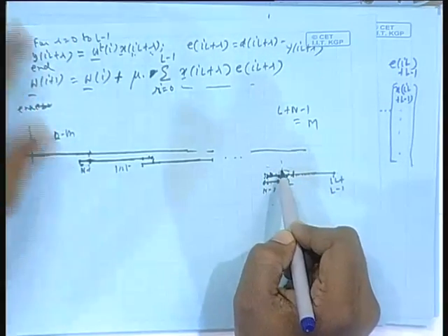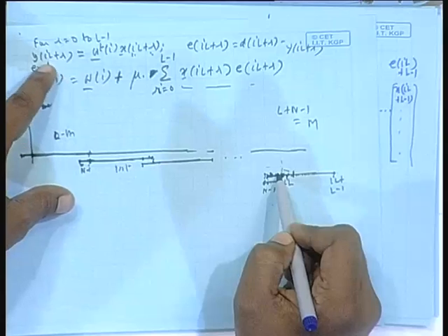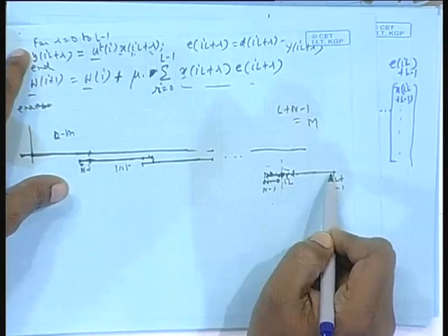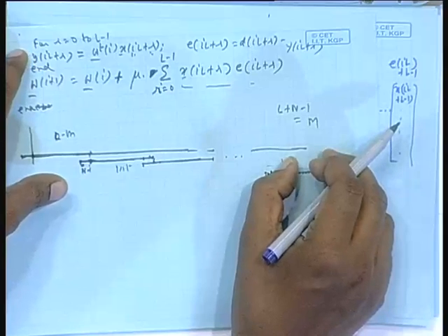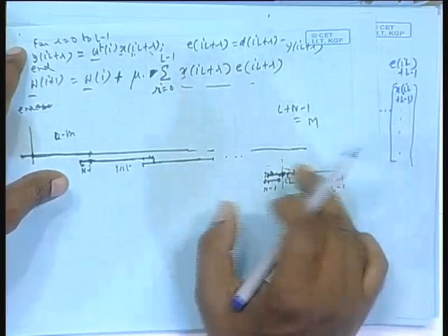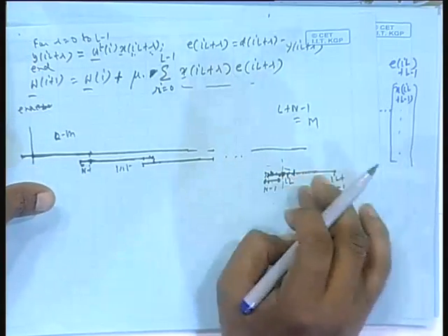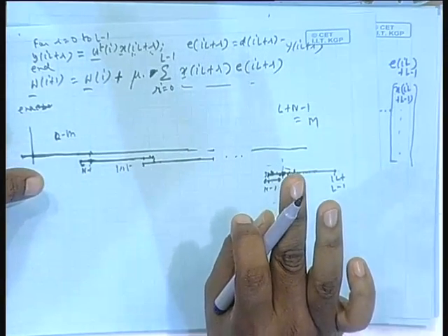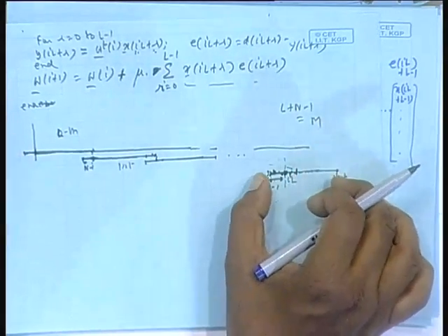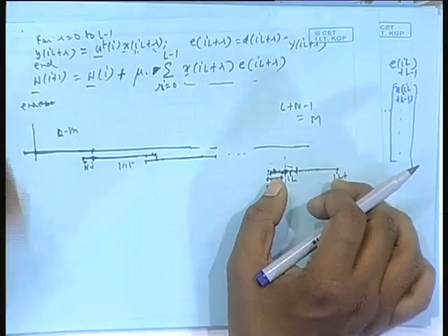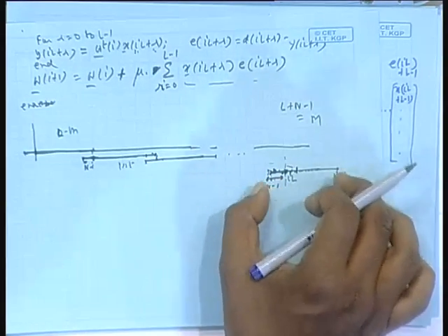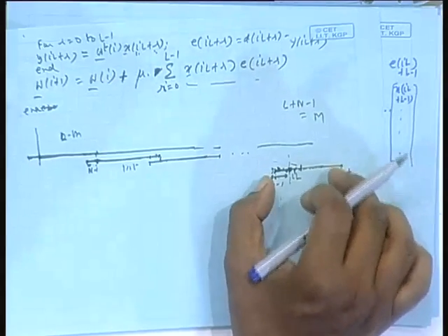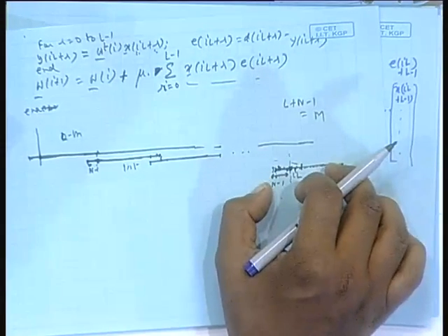Filter length was less, capital N here, and this total length is what? Capital M. So, you have to have extra zeros. Then if you do circular convolution and throw away the first N minus 1 samples, you get the correct output, isn't it? So, that time I need circular convolution means what? I will be doing in frequency domain: DFT, then multiplication, and then finally inverse DFT of that. So, I have already computed the DFT, this DFT once.